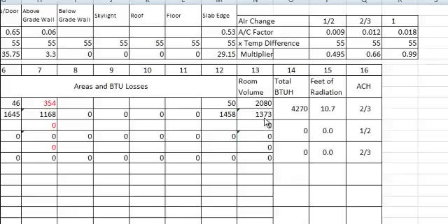So we multiply that number. Once we get 1 times this number of BTUs per hour, we multiply that by 0.66, and we end up with a figure that works out to our amount of heat lost in 1 hour, and that keeps us in line with all the other BTU per hour losses that are on this line.